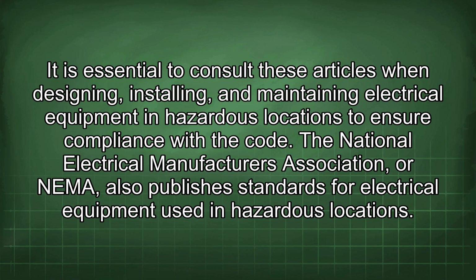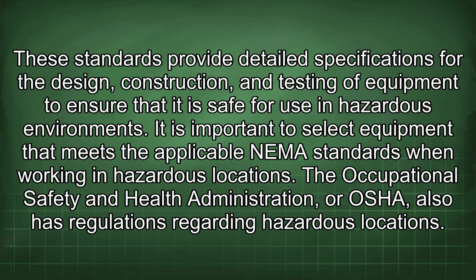The National Electrical Manufacturers Association, or NEMA, also publishes standards for electrical equipment used in hazardous locations. These standards provide detailed specifications for the design, construction, and testing of equipment to ensure that it is safe for use in hazardous environments. It is important to select equipment that meets the applicable NEMA standards when working in hazardous locations.